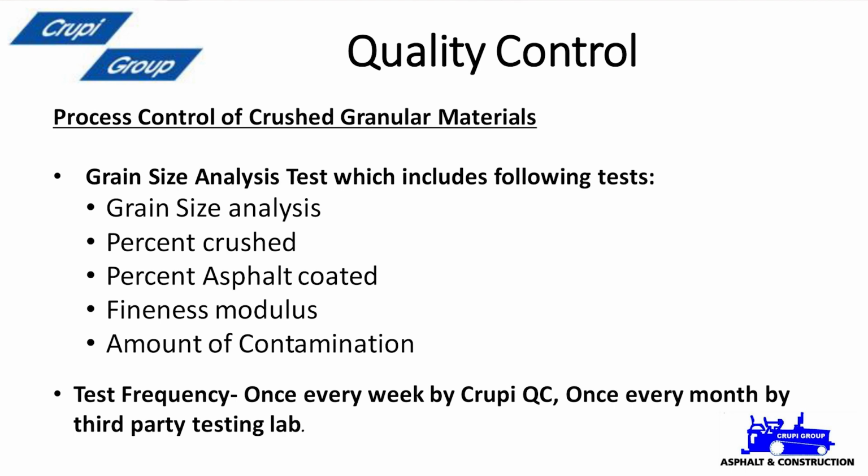One of the things that we do on the sieve analysis, we try to stay within the standard. It's percent crushed. We try to maintain above 60%. Our crushed product, when you're crushing concrete with a jaw, roll, or impactor, is over 90% all the time, so that's an easy one to pass. And then someone talked about 30% asphalt coated particles. Because it's a limit, we try to maintain at 25%, but sometimes it does creep up to 30%. One thing we see more and more often on the asphalt coated particles is how they do the test. There's strict guidelines that the MTO put through years ago.